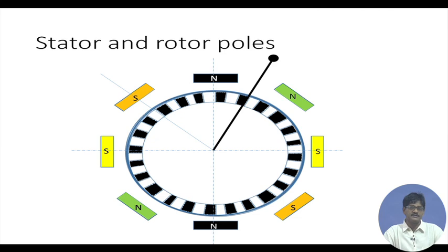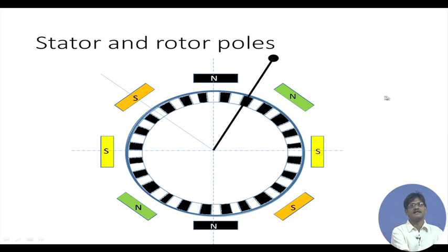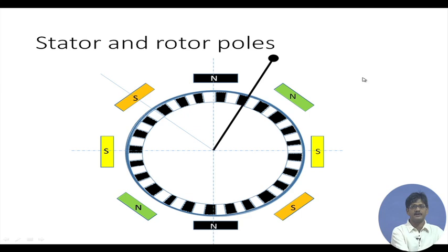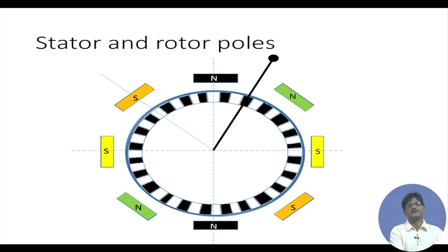So, what will happen is the nearest south pole to this black line will shift a bit, so that it is again meridionally placed, that means centrally located with respect to this line, a slight shift. Let us watch. That is it, that is the slight shift. Let us go through a rewind. So, this is the position where the black south pole is not exactly centrally located with this black line, and therefore, it shifts this much. That is the shift, and that is the step of this particular rotor.